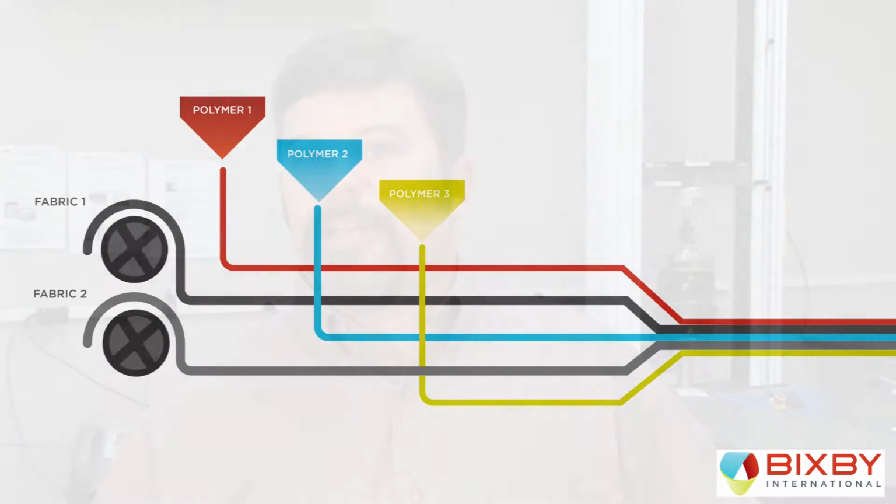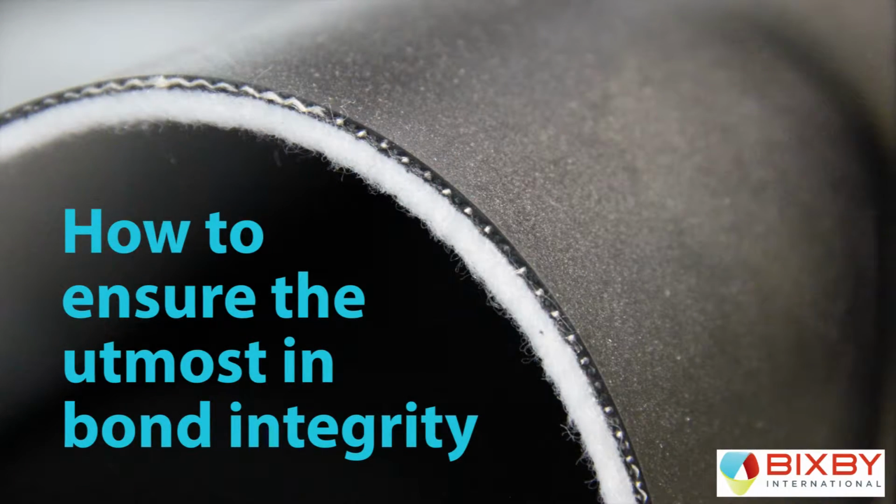Similarly, you can use primers. So you could coat a primer onto one surface, making it more compatible with a tie layer, or directly extrudable with a functional layer that Bixby would extrude, whether that be a urethane or a polyamide. This is crucial because anyone who's worked trying to bond laminate layers together understands that getting good wet out is critical to ensuring a good long-term durable bond.